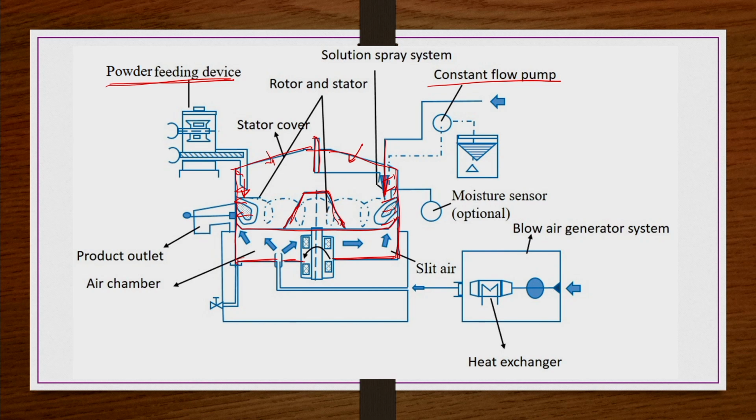So that may also take place. Or if you have a design like that, where the feed material as well as the binding liquid are coming through the container walls like this, then it is better to have a kind of high speed centrifugation rotation, so that particles are sticking to the wall, and then along these walls only the liquid is coming, so particles would be coming in contact with that liquid along the walls, and then mixing takes place.